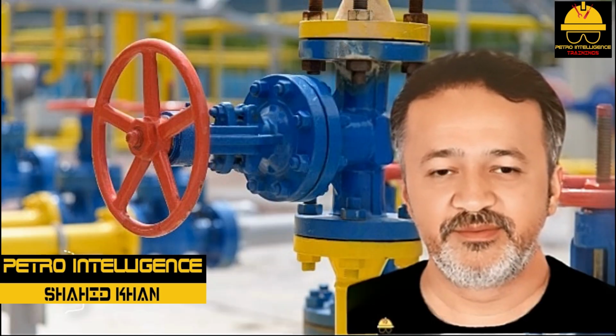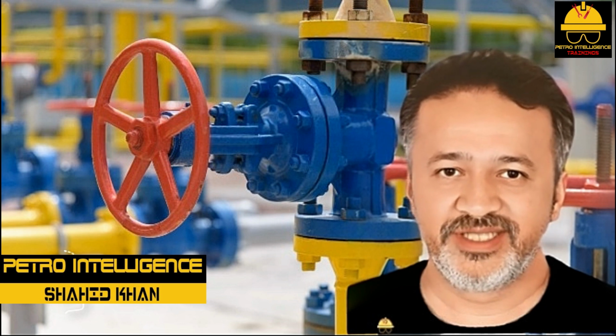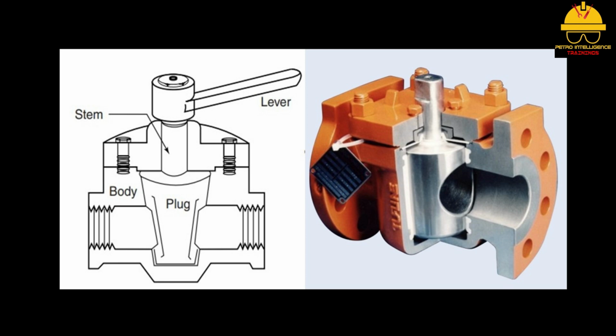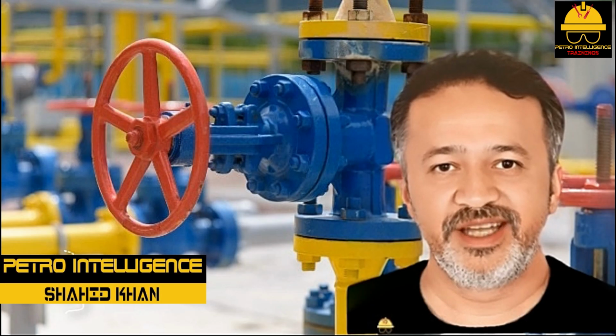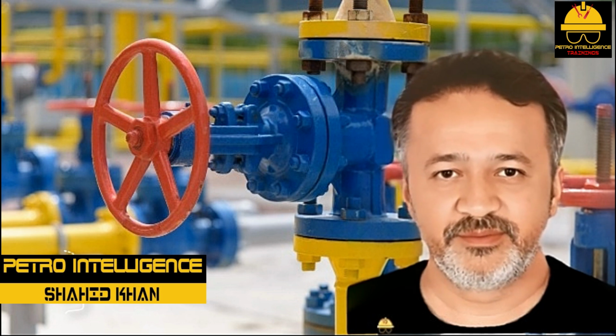Plug valves. Quick opening, 1/4 turn plug valves are very popular in the process industry. The plug valve takes its name from the plug-shaped flow control element it uses to regulate flow as shown in picture. Plug valves provide very little restriction to flow and can be opened 100% with a 1/4 turn on the valve handle. In the closed position, the port is turned away from the process flow. In the open position, the port lines up with the inner diameter of the pipe.